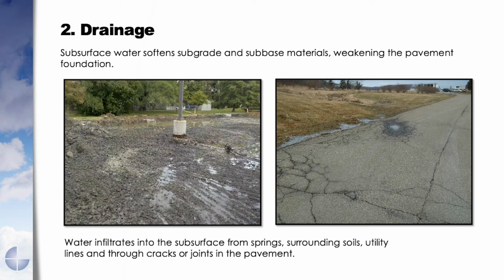The slide on the left, this is an area that we excavated. This is a ring road on a shopping mall area. When everything was removed, it was this wet. This isn't after a rainfall. This is how wet it was underneath this pavement. And I'll get into this a little bit later, how this was resolved, but that was what was causing this pavement to fail, was all this moisture underneath.